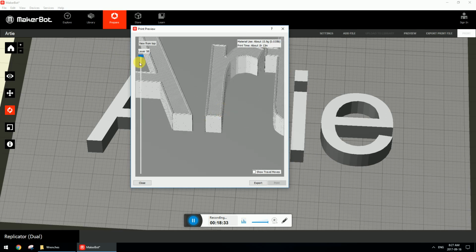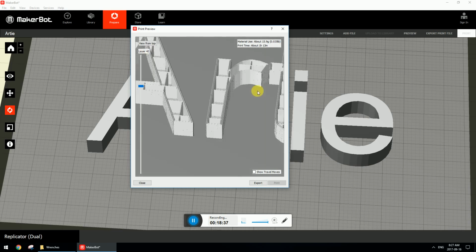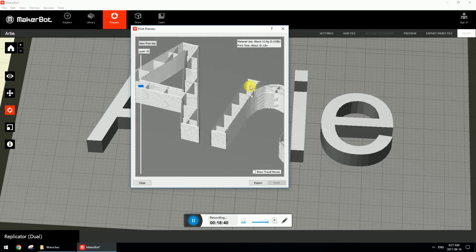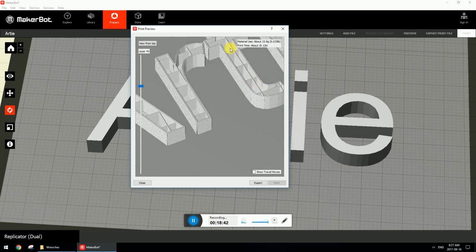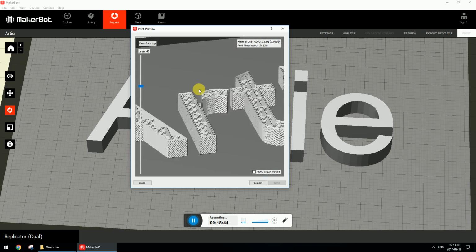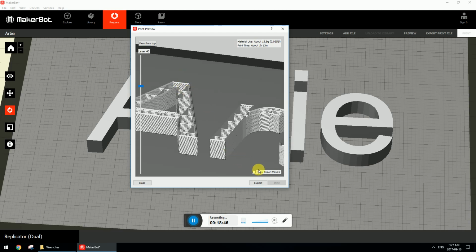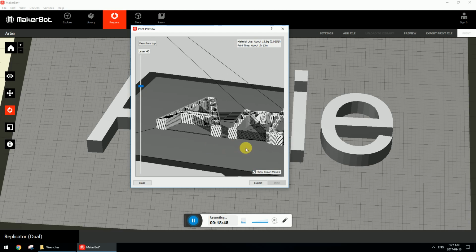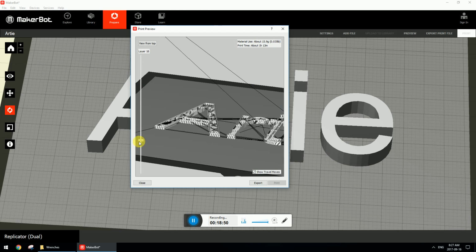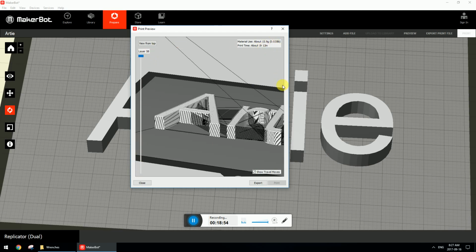So I switched to a linear type of infill, I believe. So you can see it just adds lines in there. I think you might get better results with a hexagonal. But that T would be good because it's got it right there. So again, it's all up to you. The travel moves here. Notice bridging is turned off. So there's all the travel moves there. And that's about the time there.